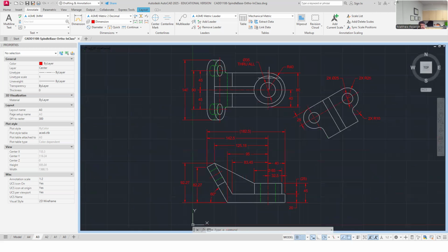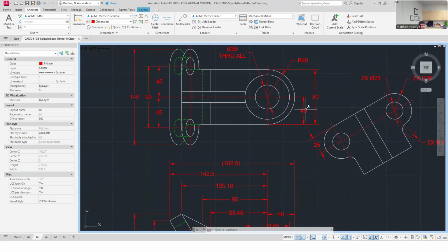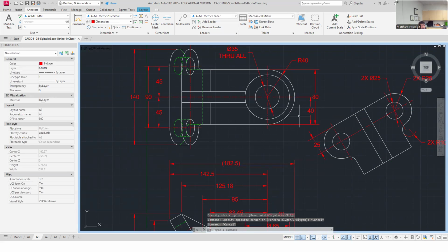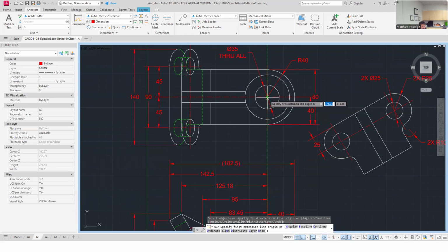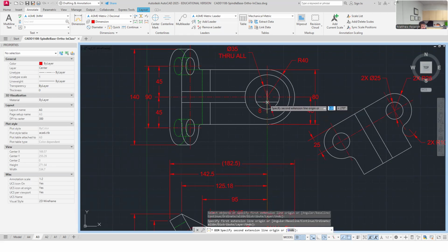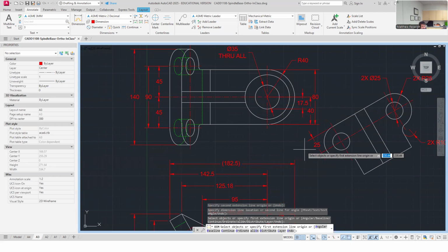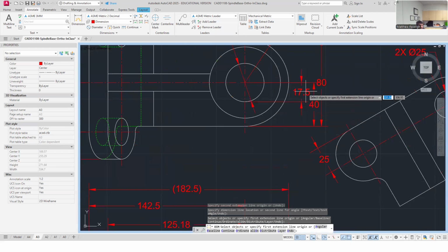And then its location is also being handled by the same, kind of. You might argue to me that maybe I need to locate it like this, and it wouldn't be wrong. It gets pretty saturated. Like to say, well, if you did the OD diameter by that, why wouldn't you do the ID diameter? And it's definitely not wrong to say, yeah, it could be located off this datum that I'm pulling things from like this. Maybe that's a little bit redundant, and some places would definitely drop that and say, we get it, it's concentric to those two, so I don't need to do this.